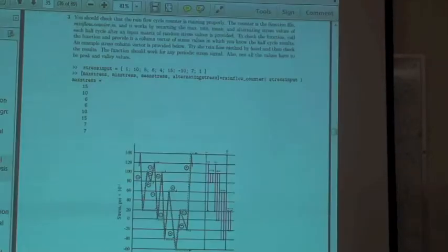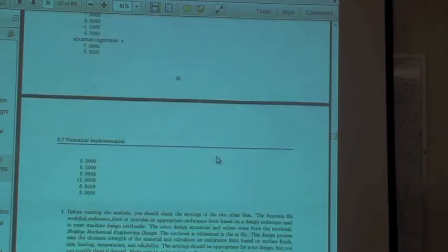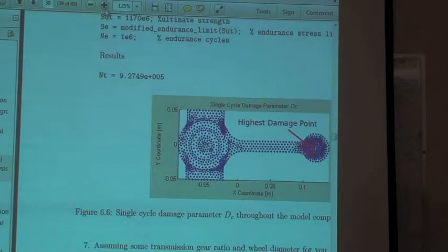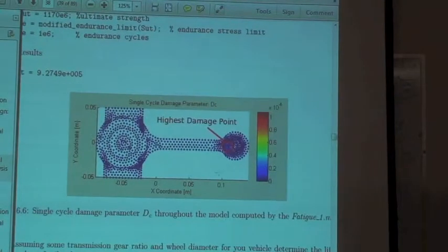So if you go back to here, the end plot is, for this example, let's zoom in, the distribution of damage per cycle. For this one, the only one that had enough damage to get over the endurance limit was this point here because it had the highest contact stress. But this was actually a safety factor of 1.1, so this is good. That means that you didn't yield, but you actually don't have infinite life.